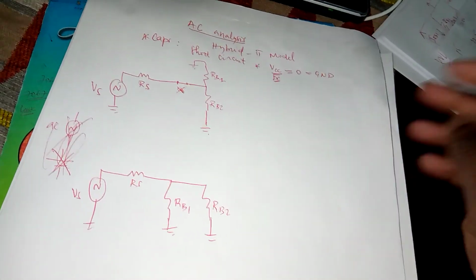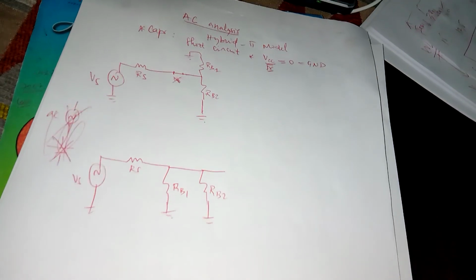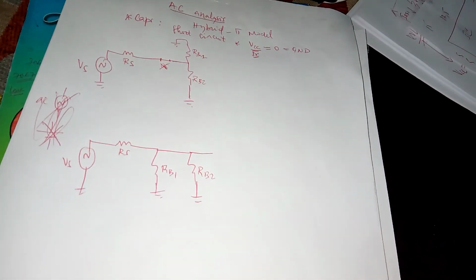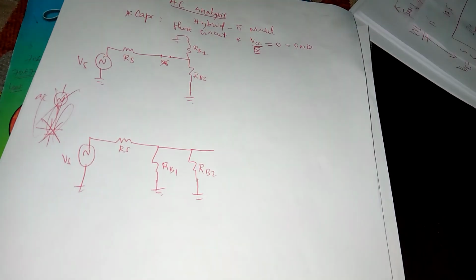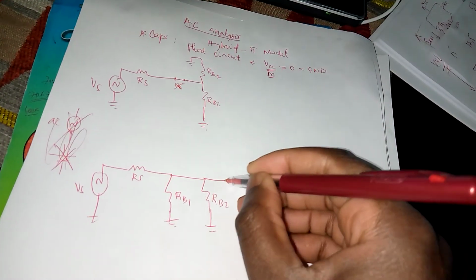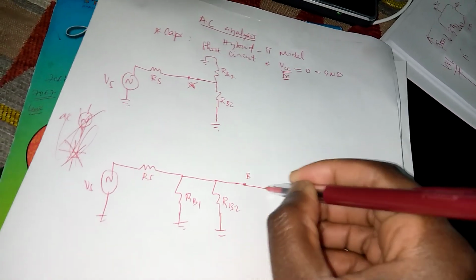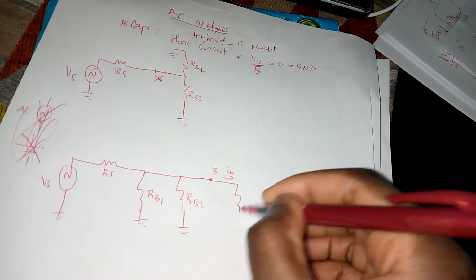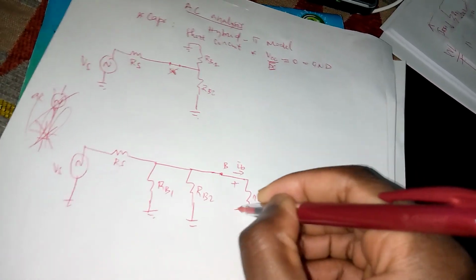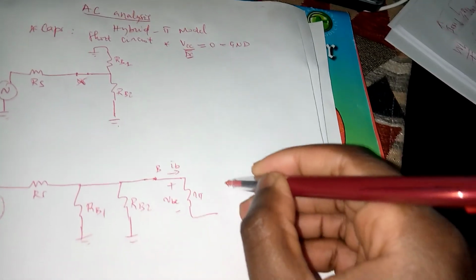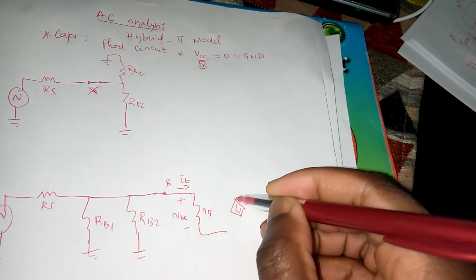Then you enter the transistor and you just replace it with the small signal AC equivalent circuit of the transistor, depending on whether it's an NPN or PNP. So in our case, it's an NPN. As we go from the base, we know that in an NPN, as we've done this many times, you've got IB flowing, you've got r pi, you've got plus minus VBE there. You have a current source, it's NPN, so IB is coming in, IC is flowing down.